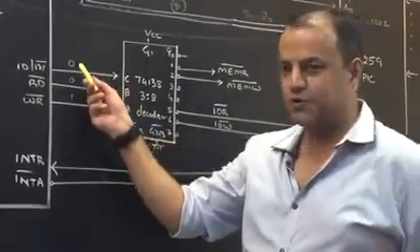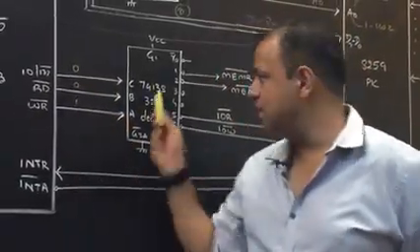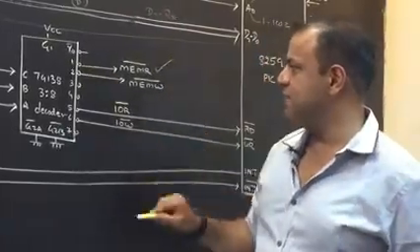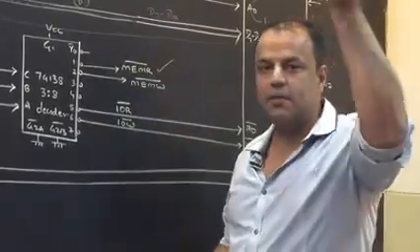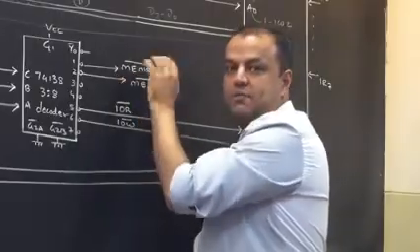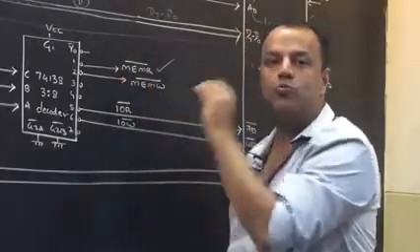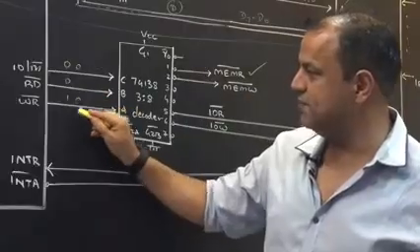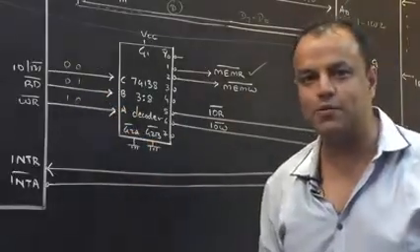So when the processor produces the combination 0, 0, 1, the output that is selected is Y1. That will act as memory read. Why did I put memory read bar? Because whichever output is selected will be 0. So they are all active low outputs. The one who's 0 is the one who's active. Are you clear? Hence the name active low. Now that you understood memory read, answer the rest by yourself.